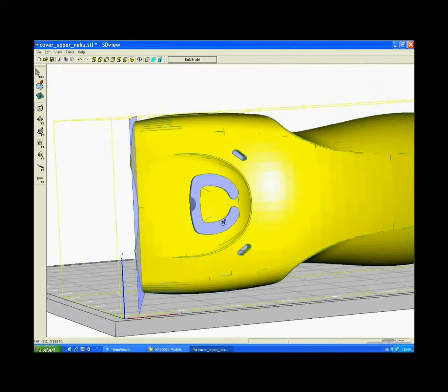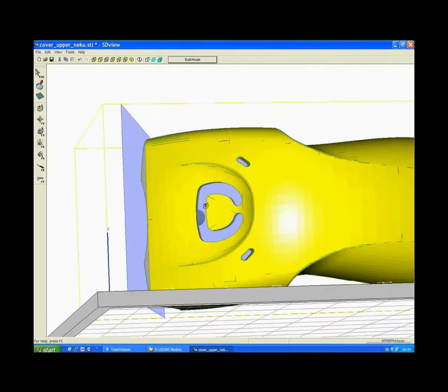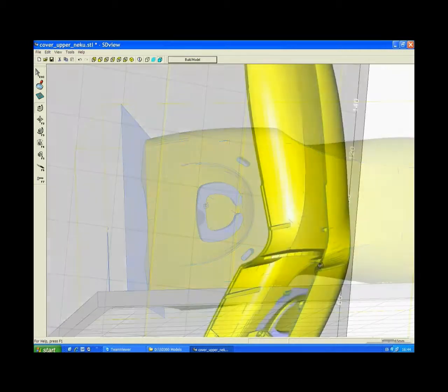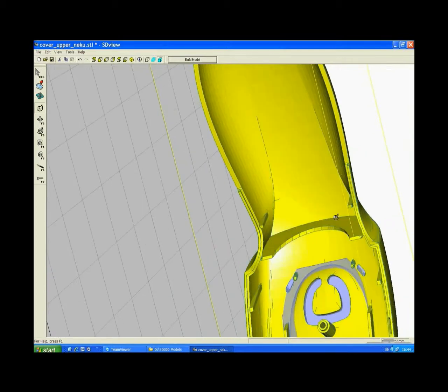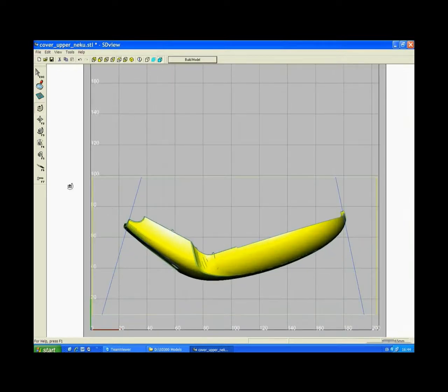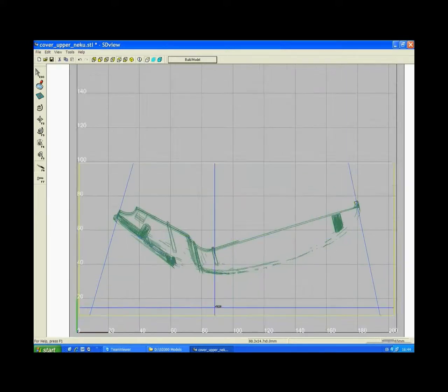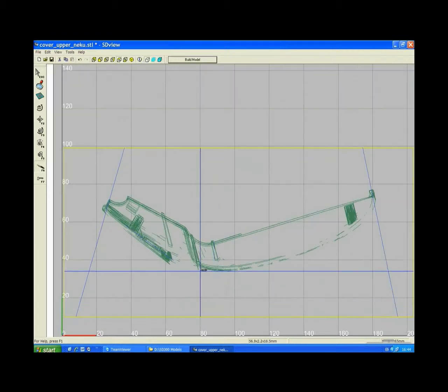As we can see, we have now closed the openings on the X and Y axes, and material peeled from the outer side of the part will not go through the opening into the inner side of the part. Finally, we may divide the inner side of the part into 2 sections running through this wall. We may select the wireframe view to detect our wall location. This is our wall. We will run a peeling cut through the wall.